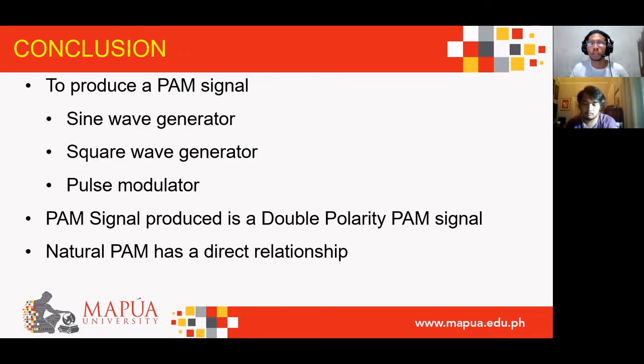The amplitude of these pulses is made to vary in accordance with that of the slower modulating signal, and the result is that of multiplying the train by the modulating signal, that envelopes the pulse height corresponds to the modulating wave. And the PAM wave contains upper and lower sideband frequencies besides the modulating and pulse signals.